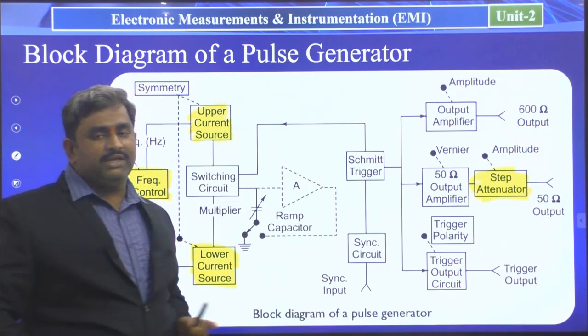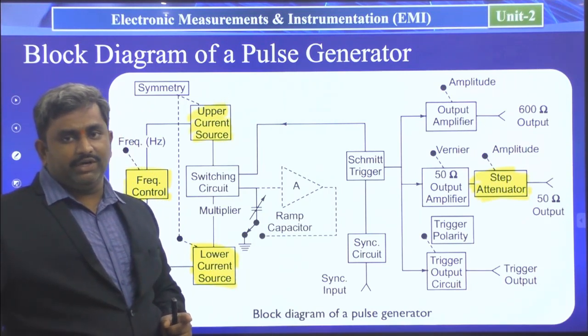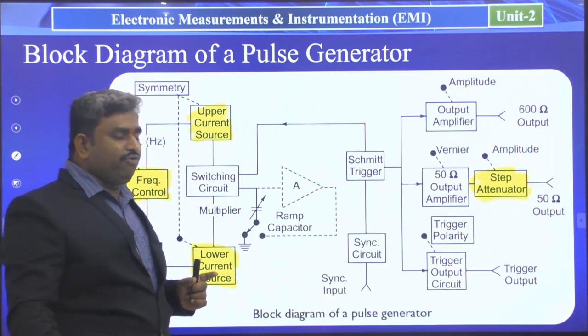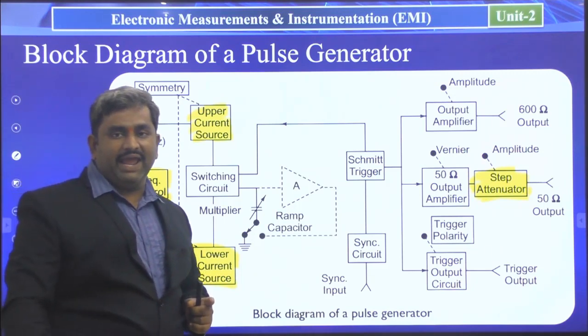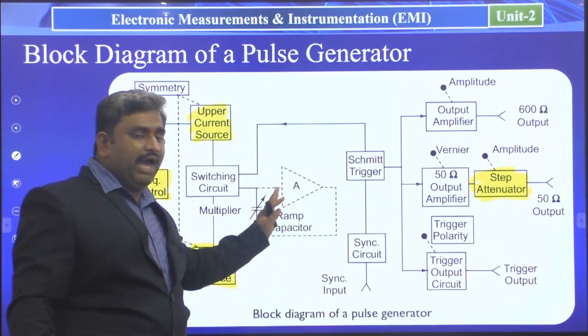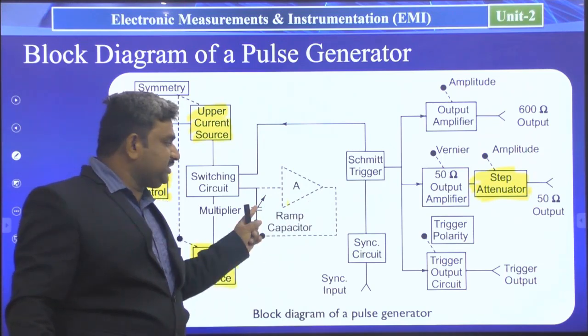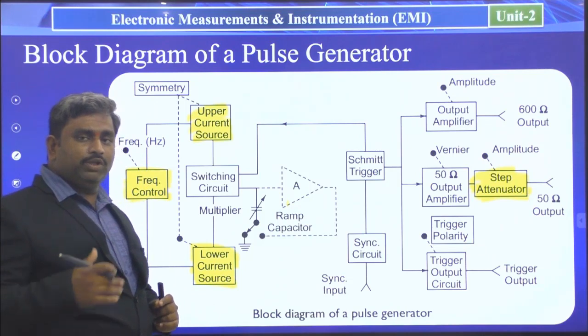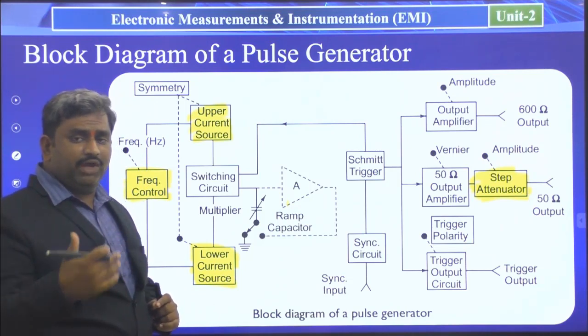But our concept is square wave and pulse wave generators. Particularly this block diagram is a pulse wave generator. So for that reason we don't need the triangular waveform output. We have to remove that integrator part, which is represented with these dotted lines. Now we have to bother about the square wave output.